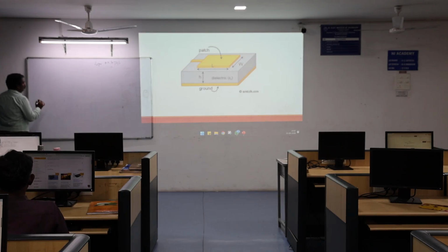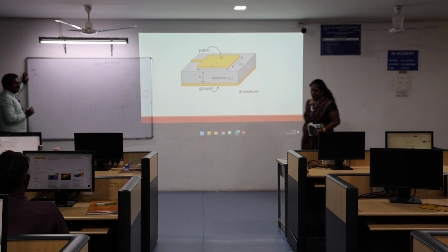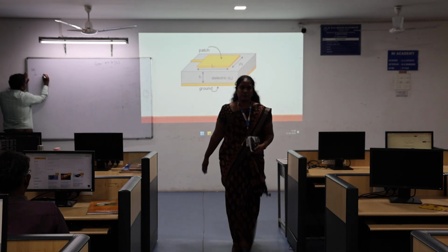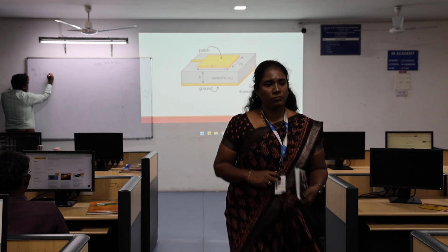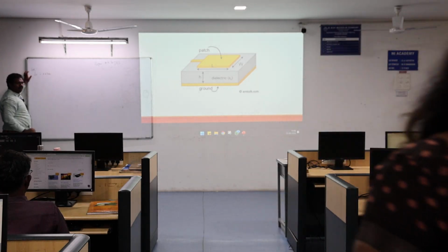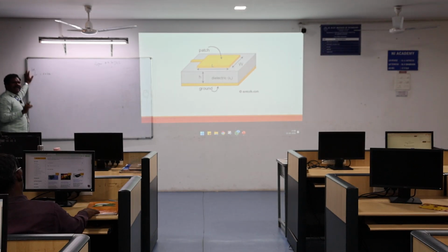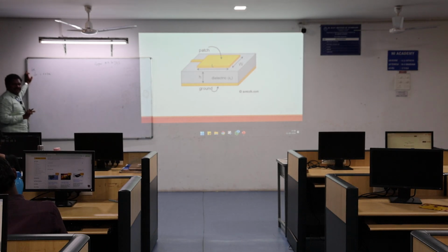While designing a microstrip patch antenna, first you need to know the elements. What is your operating resonant frequency? That is FR, the resonant frequency or operating frequency. I have chosen the operating frequency of 2.4 gigahertz, so the antenna is able to operate in the 2.4 gigahertz frequency range.